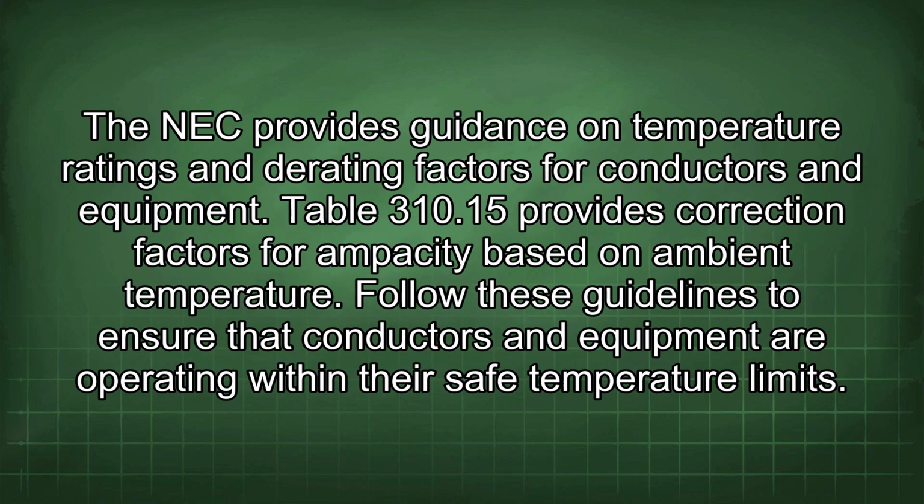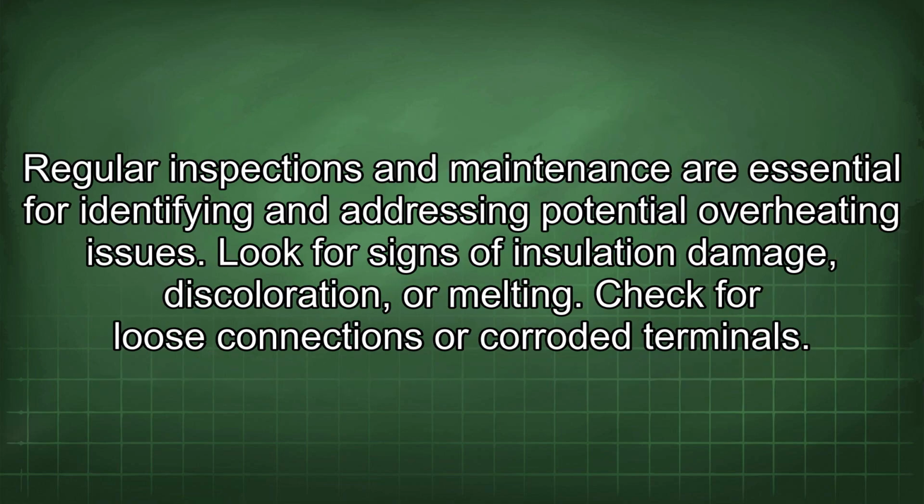The NEC provides guidance on temperature ratings and derating factors for conductors and equipment. Table 310.15 provides correction factors for ampacity based on ambient temperature. Follow these guidelines to ensure that conductors and equipment are operating within their safe temperature limits. Regular inspections and maintenance are essential for identifying and addressing potential overheating issues.